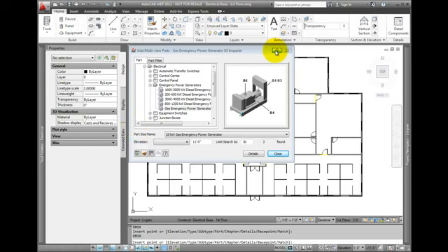The MV Part palette will appear. This is a floating palette and can be pinned into place or set to auto hide. Leave it pinned. The tool from the palette is set to jump directly to the category for generators. Select the Emergency Power Generator Gas. This is important. Check the elevation. This is the only thing you really need to know about working in 3D. This sets the height or Z elevation of the part based on the insertion point of the part. Set this to 0 inches so it is placed on the ground.